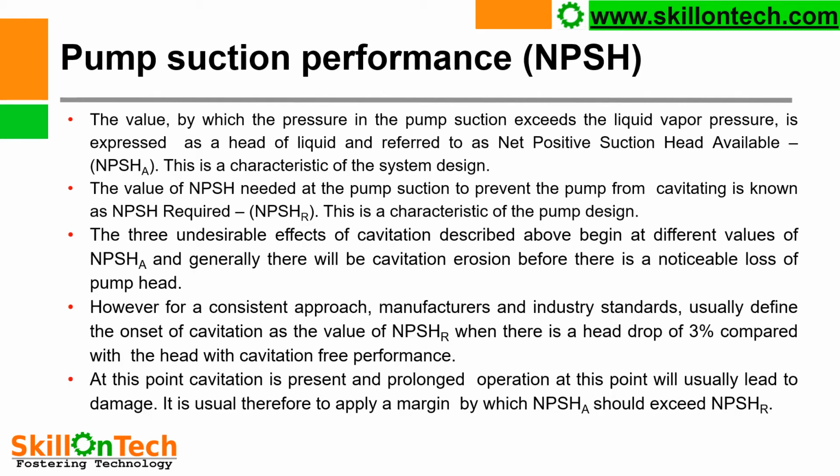Pump suction performance (NPSH). The value by which the pressure in the pump suction exceeds the liquid vapor pressure is expressed as a head of liquid and referred to as the net positive suction head available (NPSHA). This is a characteristic of the system design. The value of NPSH needed at the pump suction to prevent the pump from cavitating is known as NPSH required (NPSH-R). This is a characteristic of the pump design which is given by the pump manufacturer.